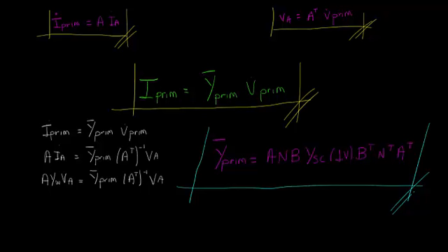Beautiful, isn't it? At the end of the day, all you need is the short circuit impedance of each pair of windings and the turns ratio or voltage ratings of the windings. The incidence matrix A can be derived based on the connection of the transformer to its terminals. Now, let's understand how we can specify the transformer parameters in OpenDSS.